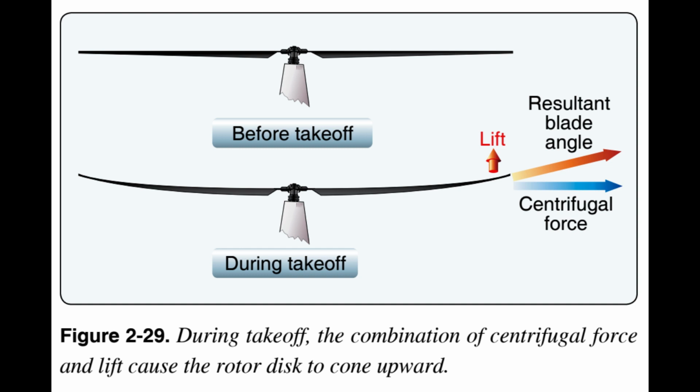The action results in an increase in rotor RPM, which causes a slight increase in lift. Most pilots arrest this increase of RPM with an increase in collective pitch. This increase in blade RPM lift is somewhat negated by the slightly smaller disc area as the blades cone upward.